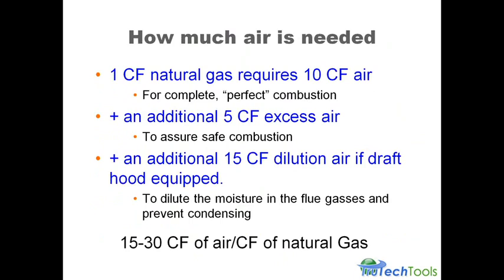And what we're doing here, when you think about the gas and the air mixing together, imagine you've got 100 blue marbles and 100 red marbles in a jar, and you shake up the jar. What are the odds of a blue marble and a red marble touching together on every single marble, right? The odds are pretty slim. So if we increase the amount of blue marbles, and the blue marbles in this case would be the air, you know, we put in 50% more blue marbles. Well, the odds of a red marble contacting a blue marble when we shake that jar up are much higher. And that's what excess air is basically for. It's extra air through the combustion process to assure complete conversion of the carbon to carbon dioxide in the flue gases.